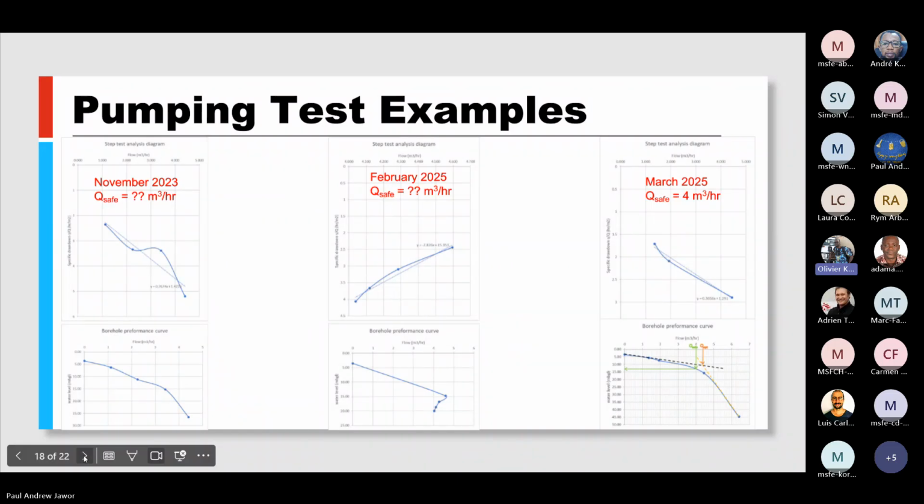We generally get this information from these curves when we start noticing these sharp dropping trends. So generally, that is the idea behind why we ask to define Q1, Q2, Q3, Q4 as we saw previously, and then when we follow the pumping rate and ensure that the drawdown values are collected accordingly, we should be able to plot this curve as we see here, which is a curve of the flow versus the water level.